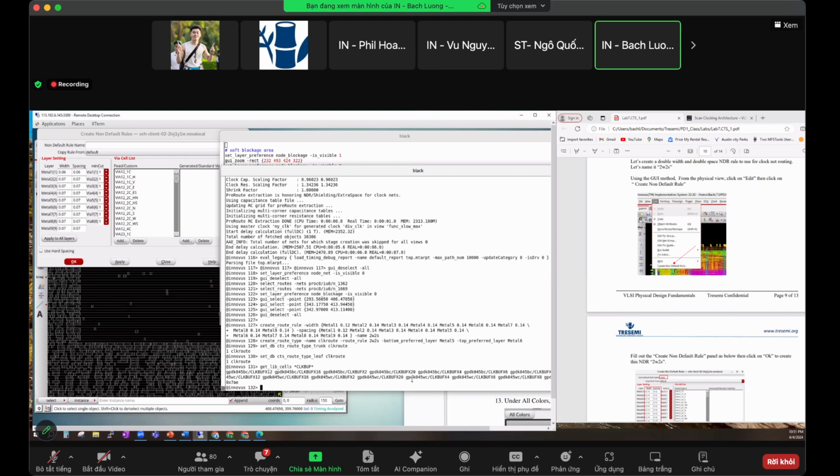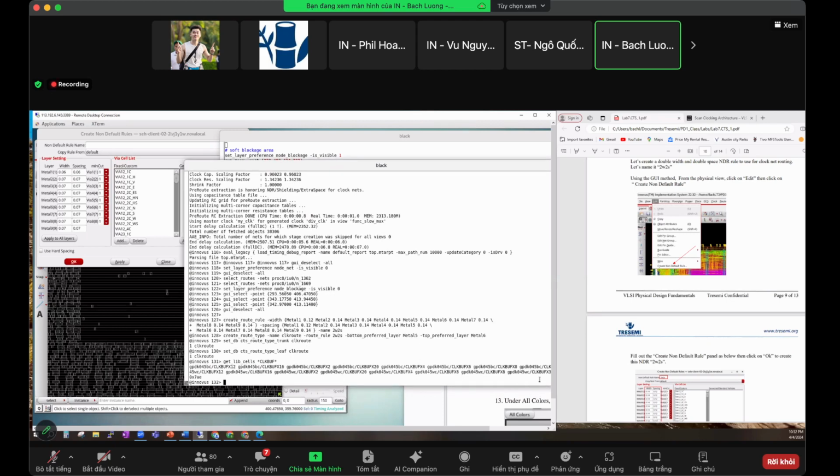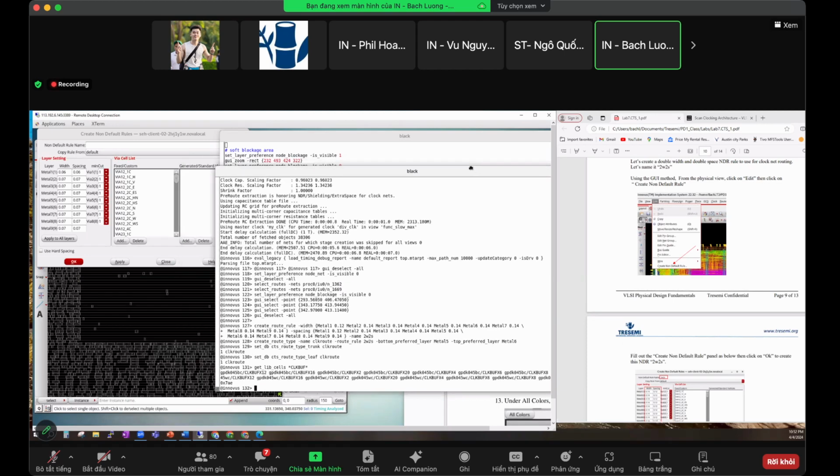So basically the highest is above 20, and the lowest is 3, 2. So is there 1? Okay, so normally we don't use the highest one or the lowest one. These tend to become the crosstalk victim, and the big ones become the aggressor. So in the lab, I had you guys use just 3, and you can expand it a little bit more if you want.